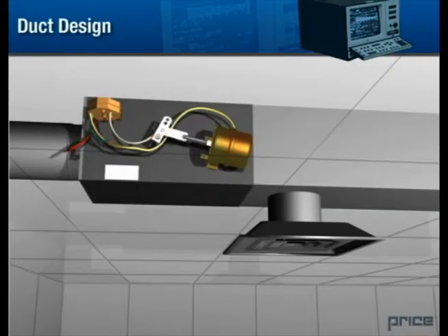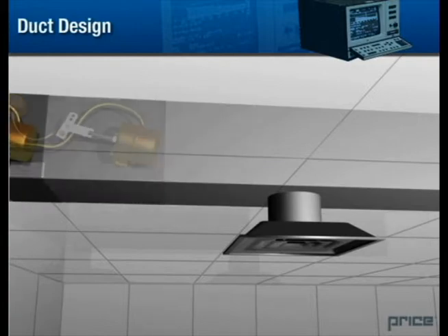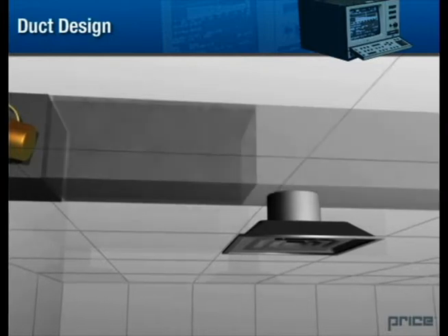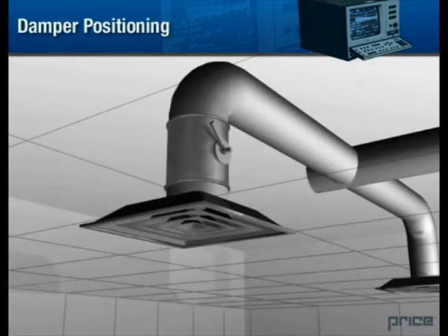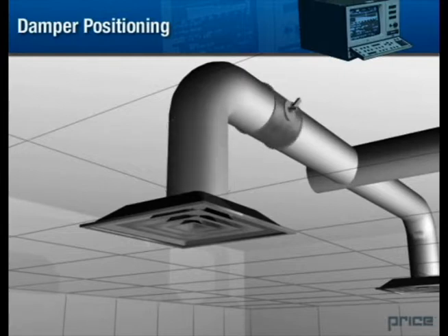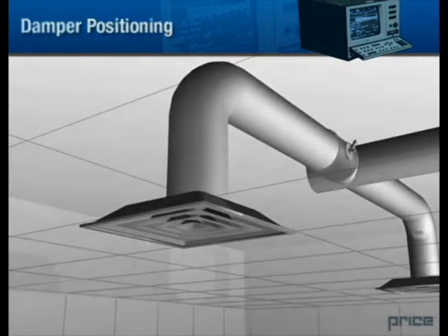Scenario 4. Poor duct design. If a diffuser is located too close to the terminal unit, damper and fan noise will be transmitted to the environment via the ductwork. It is recommended that there should be at least 3 duct diameters of distance before your first diffuser is placed. A reasonable amount of lined ductwork should be used to dampen noise. Scenario 5. Damper placement. Because dampers create turbulence and noise, it is important to position them as close to the branch or takeoff as possible. The further away the damper is located from the diffuser, the better.